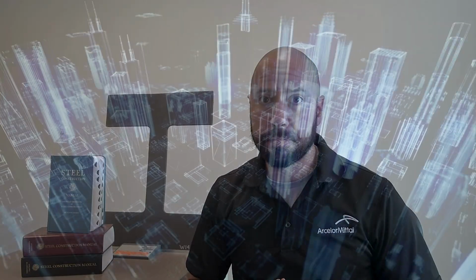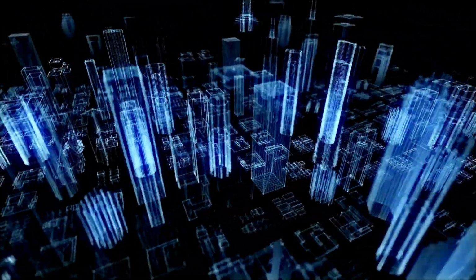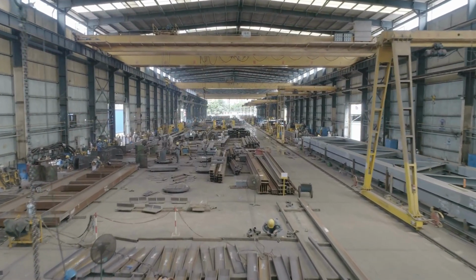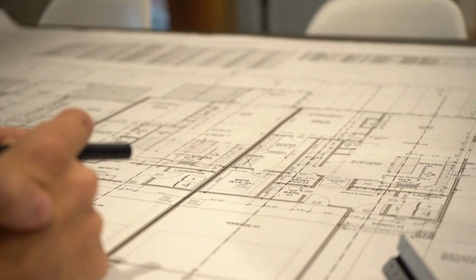Now that we have the basics covered, let's talk about which grade of A913 is right for your project. As the structural engineer, it's relatively simple for you to figure out how much weight you're going to save using different grades of A913. But there are other variables to consider, like weldability, fabrication costs, and fabricator experience. These other variables will make it more difficult for the engineer to determine what grade of A913 will be the most cost-effective. One solution that's been implemented very effectively in the past is the use of a multiple column schedule.